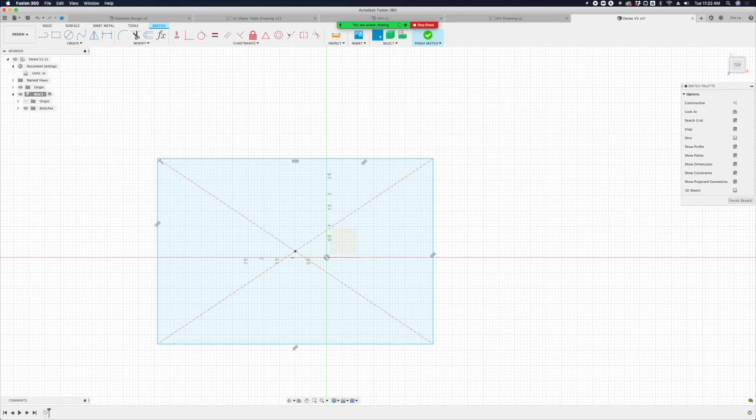Yeah, okay. These little gray things here are constraints. They match these symbols in this part of the toolbar. You've got parallel, so all these lines are parallel. This one is horizontal, and you can match them to these here. If you have a line drawn that's close to the x-axis or the y-axis, it automatically snaps to whichever one it's a little closer to.